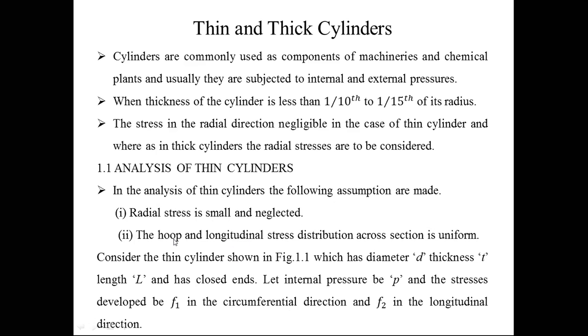Hoop stress and longitudinal stress: in cylinders, whether thin or thick, there are two important stresses. One is the circumferential stress, also called hoop stress. This acts on the diametrical section, and the other one is longitudinal stress. These two stresses are very important in the analysis of thin or thick cylinders.